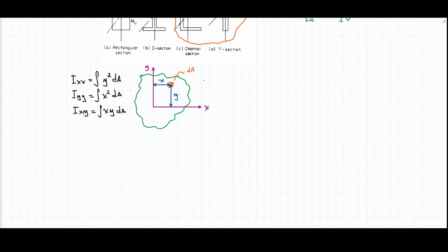Now, this figure here represents, or these formulas for the second moment of area and product second moment of area are defined by this figure here. So we have a definition of the formula we had and this one. But now our task is to define how the principal axes are oriented in case that x and y are not those principal axes.